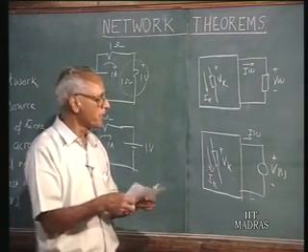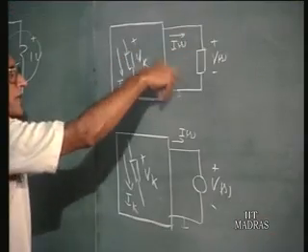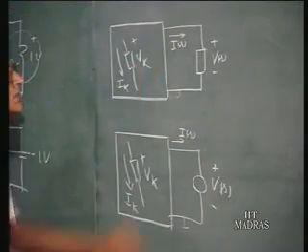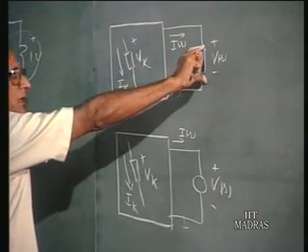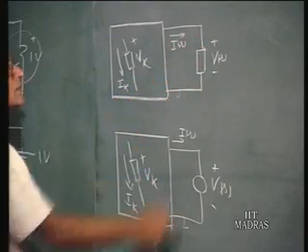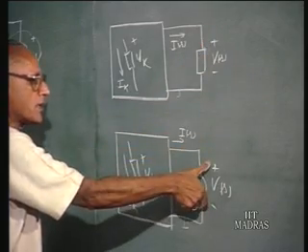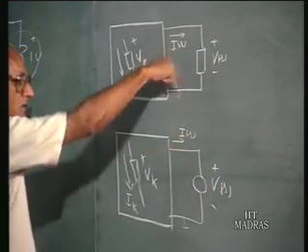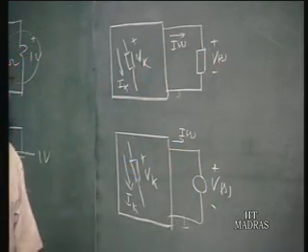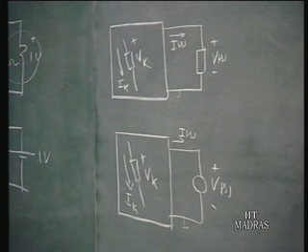Similarly, if you are using the loop equations, the other loop equations are the same. In this loop equation corresponding to Ifs, across this particular element you have some, for example, Zs times Ifs, something would have written, and now whatever solution you had obtained for this is now incorporated here. So the stipulation for this loop equation is consistent with the solution. The other loop equations are the same, therefore the solution for the other element responses will be the same. This is the principle of the substitution theorem.